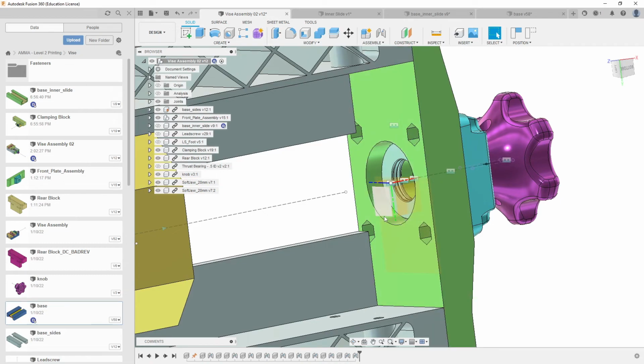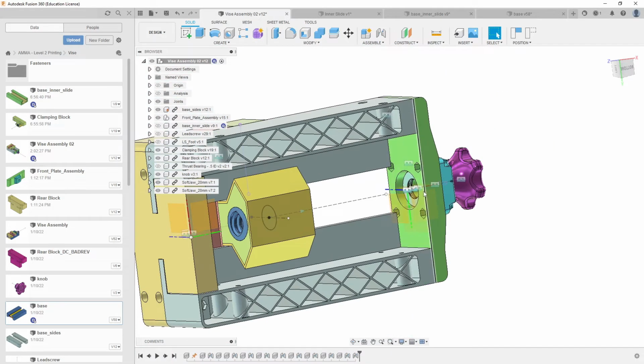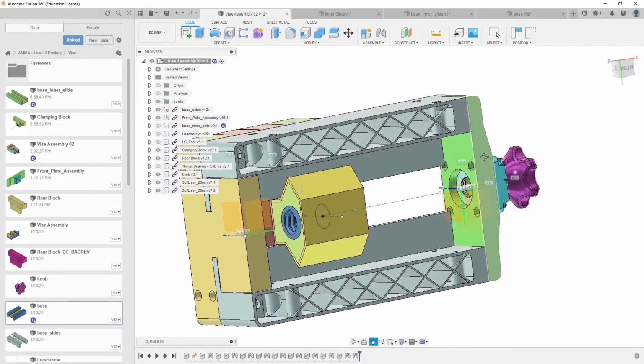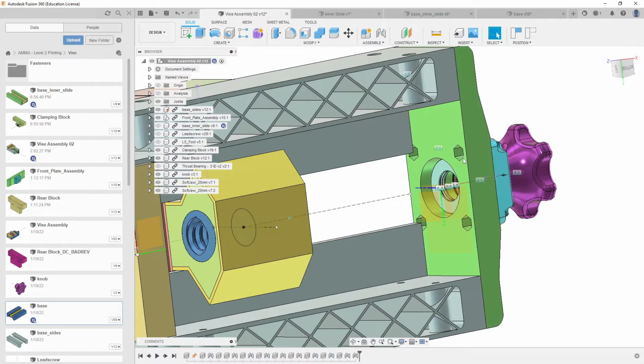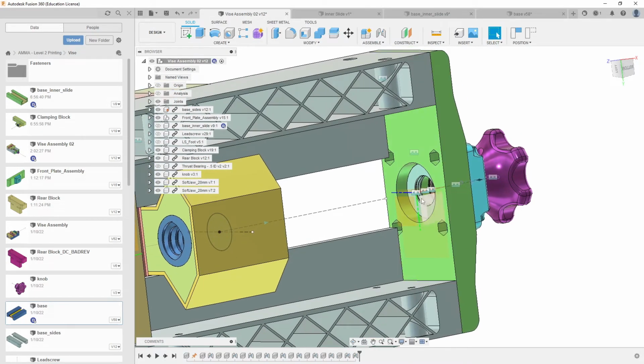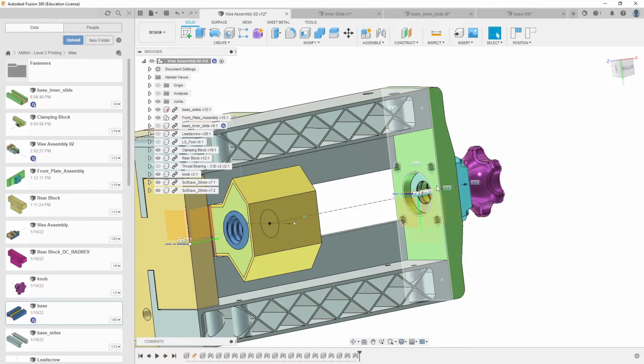I would like it to be right in the center of this circle. This circle is the main center point. We don't have a main circle center point through our part, but I could add one. I could add an alignment sketch, another big topic. So I could add an alignment sketch to my existing model. So when it comes to joining things together, which I know we have not done yet, I have something that I can anchor the two things together. So, a concept to come up in the not so distant future.